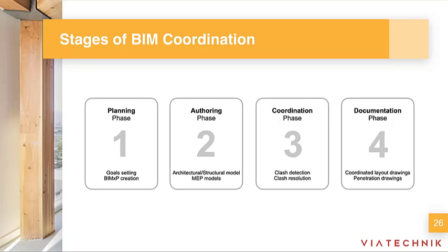This coordination process is repeated until there are no more pending conflicts, and that's when we say that the model is clash-free. Once the coordination is completed, and we are completely clash-free, we can say that we are able to sign off and the team is ready to develop the coordinated MEP layout drawings and the final fabrication installation per those drawings.